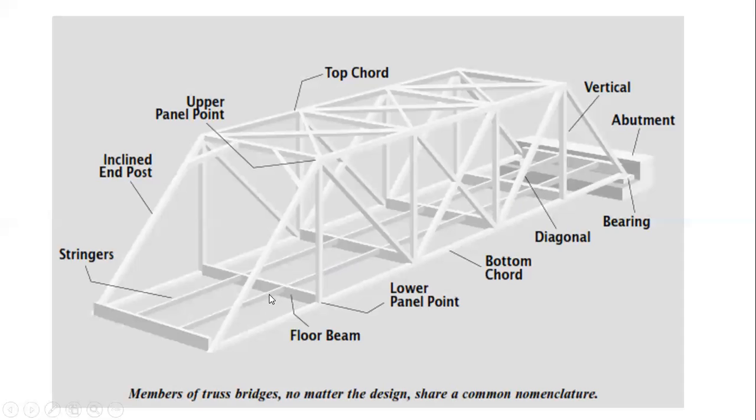This one is here, the other one is this one, longitudinal members. These longitudinal beams are called your stringers. Then over these stringers, we provide the railway sleepers in this direction, over it at regular intervals. Then over the sleepers, we have to provide the railway line. Clear?